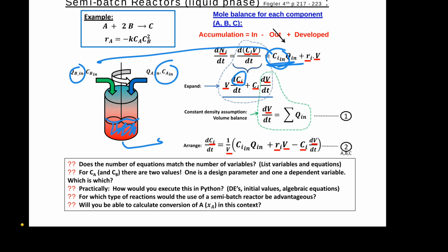To initialize your integration, regardless of which numerical integration function you use, you need the initial concentration of component A and component B inside your reactor. So if you don't get confused with the different concentrations and you substitute the correct concentration everywhere in your rates and in your integration boundaries, all will be well.